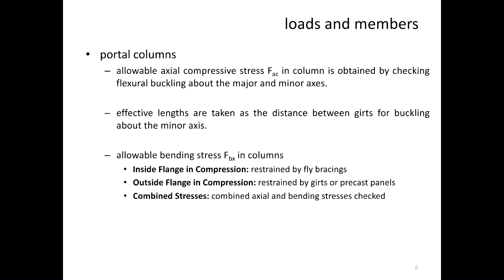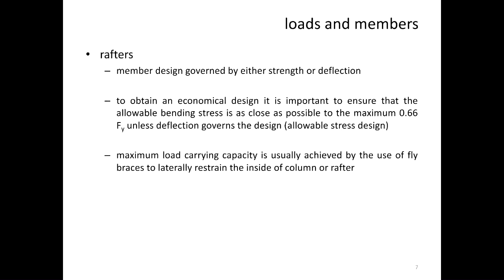Yes, they are, because it's part of the envelope. It's load bearing. They carry lateral and gravity load as well, because the roof sits on it. It depends how it's been built. So it just depends on the design. Sometimes you have the portal frame in. We've got different types, and we'll talk about them later. We've got precast and tilt-up construction, so they are built differently. We'll talk about that a bit more in week 9 or 10.